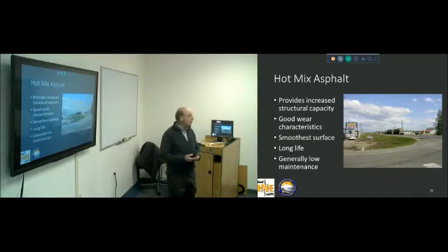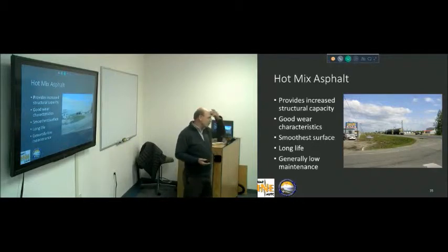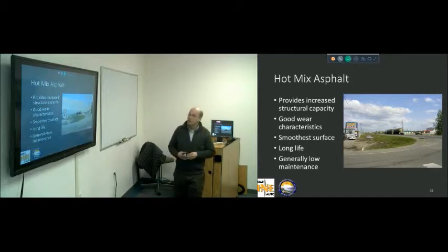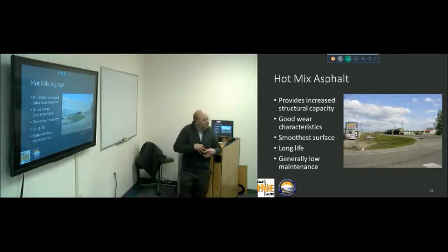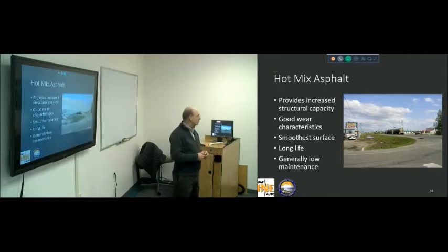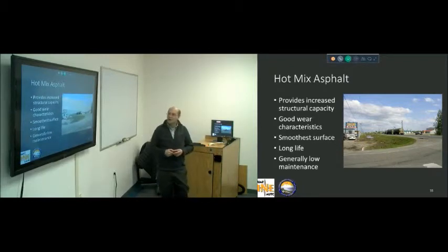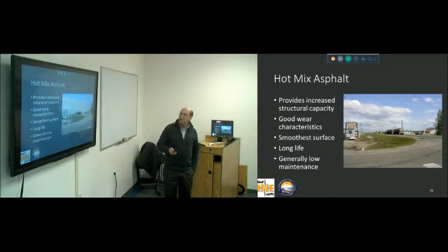They typically have a long life. We typically like to get, I think our average is between 12 and 15 years right now, although we have seen some that are in excess of 30 years old, but we're getting a lot better performance out of those overall. But they are more expensive. And in general, they tend to be pretty low maintenance. There's a little bit of crack sealing that we need to do in there, but that's pretty much all we have to do to maintain those.